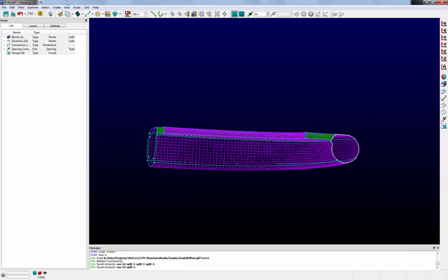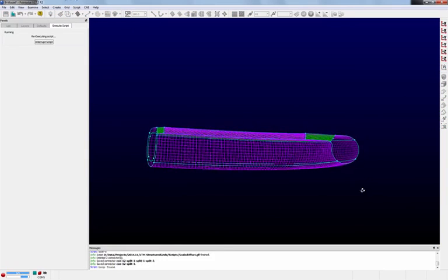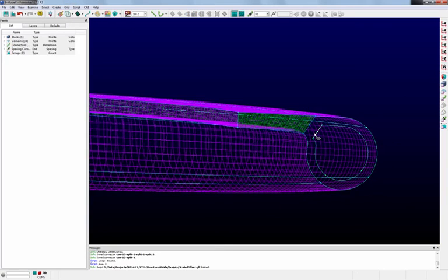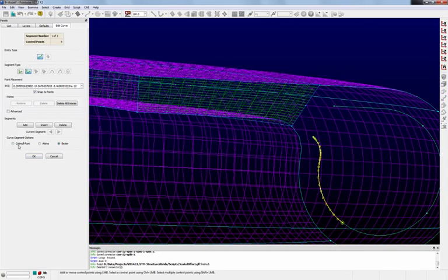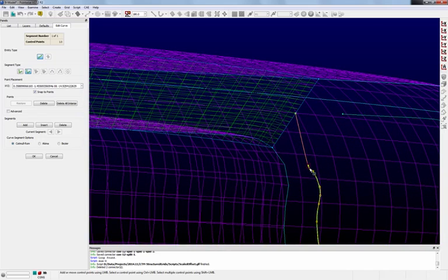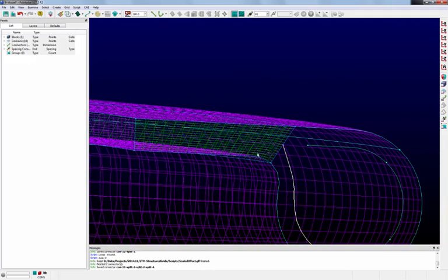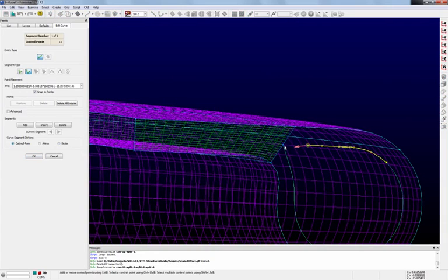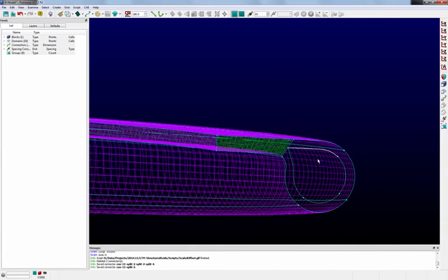So highlight those, script, Scaled Offset. We're then going to just delete these 2 points, and then Alt-EC, change the curve type, go up here. We're going to delete that point and delete a couple of these, and then maybe move this point around. And again, this is just to make a nice smooth curve. This isn't going to be an optimal grid. I'm making it fairly quickly, but with a few more minutes you can improve the cell quality a good bit.